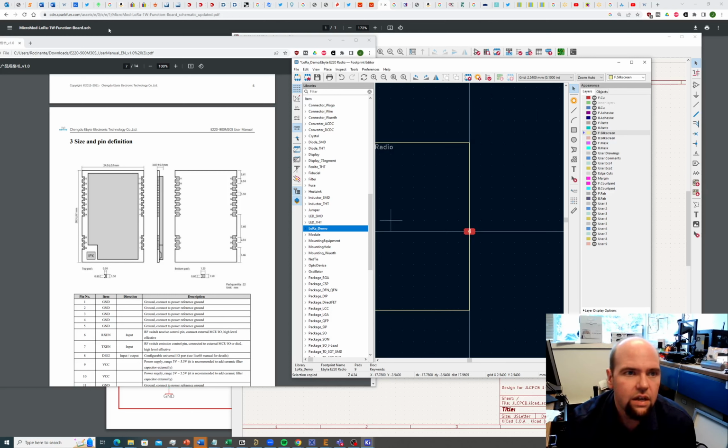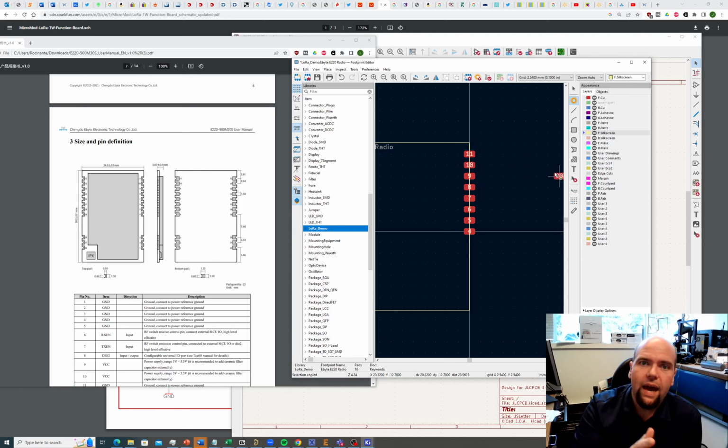So now if I do place add pad, it should start with 5, and it should now be referenced to that previous one. So 5, 6, 7, 8, 9, 10, 11. See how slick that is? So when you change the pad reference, every pad you do is going to be relative to that. It makes it really easy to do these kinds of things.